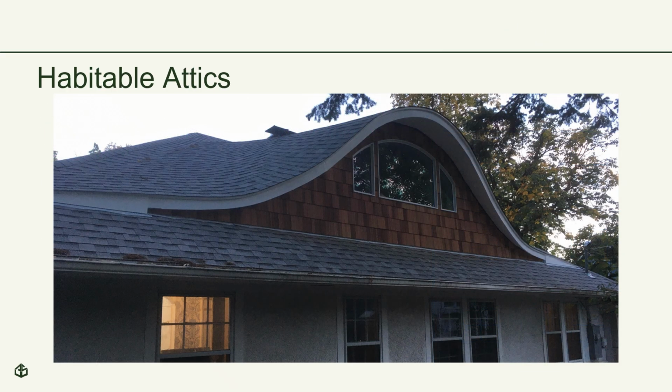Here's an example of a habitable attic. This would not be considered a story per the IRC because the roof structure also transfers lateral loads to the story below, so there is no need to provide brace wall panels for the habitable attic.